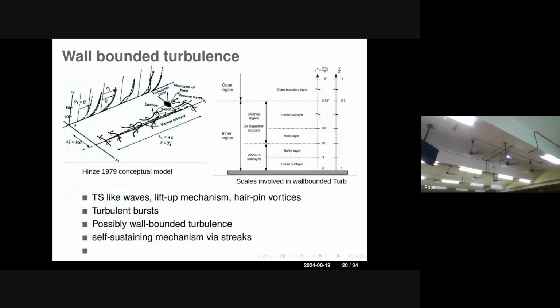And the scales also have an instability mechanism that develops, with either hairpins or puffs happening if it is a complete channel. Puffs come, go out and so on. If it is just plain walls, a hairpin comes, bursts and creates turbulence in the system. Based on that, you will always have a very complicated multi-scale nature in terms of boundary layer behavior.